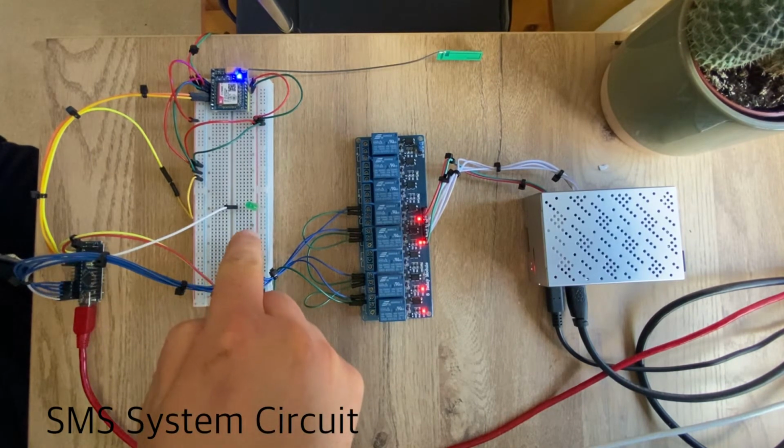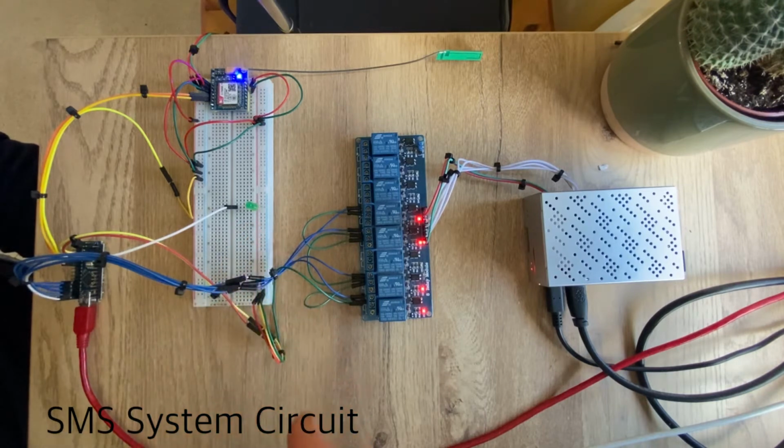Here we also have an LED to give an indication of when an SMS has been called. When an SMS is called, the LED will stay on steady until the AT commands have been pushed to the SIM800C. When this is done and this text message has been sent, the LED will blink to indicate that the function has been successful, and it goes back to waiting until the next relay output.